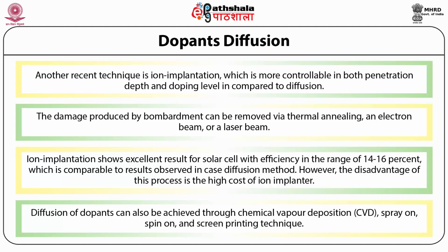A uniform layer of dopants, that is phosphorus and boron doped oxide, can be deposited on either side of the silicon wafer through the CVD technique, which follows the drive-in step and provides a much more uniform profile and controlled dopant concentration. So the advantage is that the junction on the front side is made, while the disadvantage is that this process requires highly pure and expensive gases.